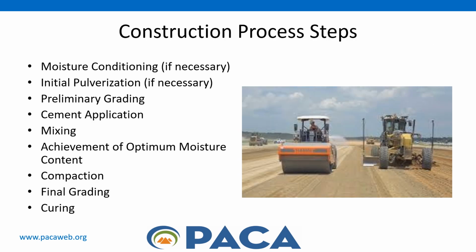The construction techniques for cement soil stabilization are very similar to those of a mixed in place cement treated base or full depth reclamation. The timing of the operation is less stringent when dealing with cement soil stabilization. Consideration must be given to preparation before the mixing operation. Guide stakes should be set to control the area that is to be stabilized with the cement, and it also is important to ensure that each truck places the required amount of cement in the appropriate area.